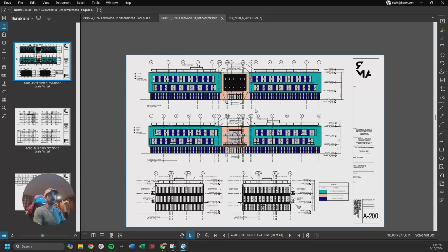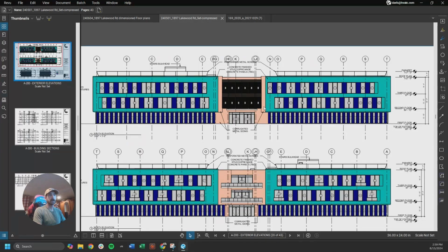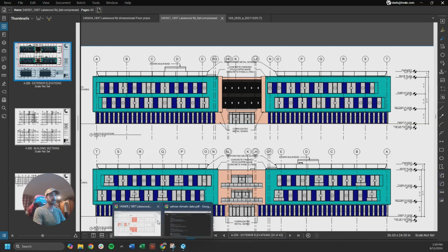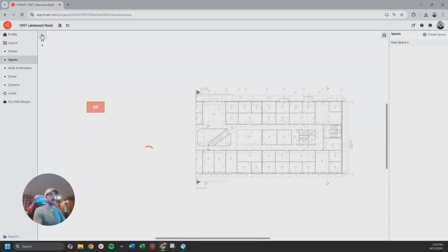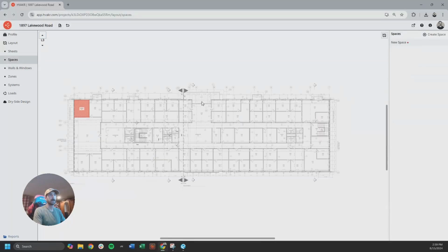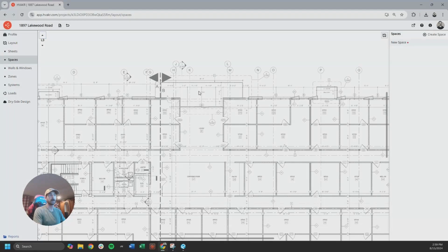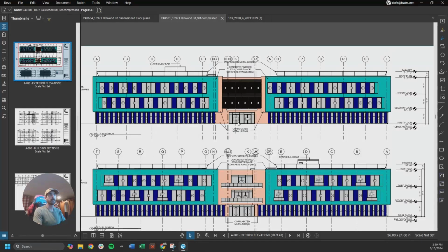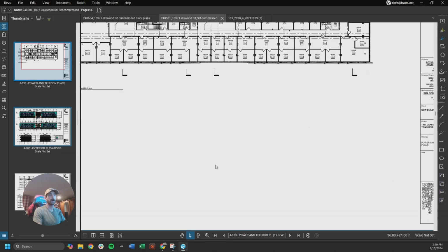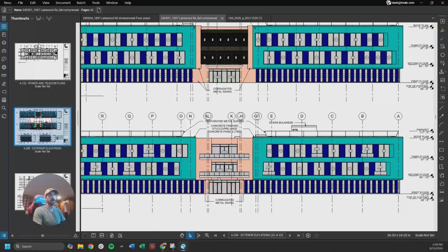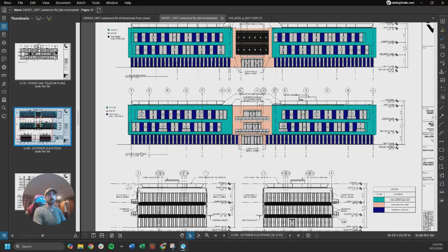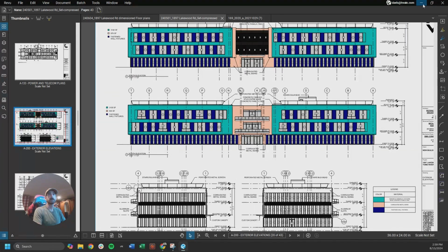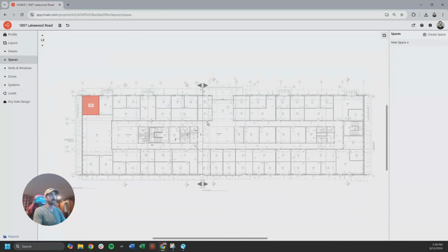Okay, I'm not seeing a compass anywhere, but if you look at this setup, they're saying this is south elevation, and this matches this south side right here. And if I look up, I've got a balcony up here on what I'm assuming is the north elevation, so I can confirm that by looking at this drawing here. The balcony is here, which is north elevation. So plan north is true north as far as I'm concerned. That's a very easy tweak if I need to correct for that.